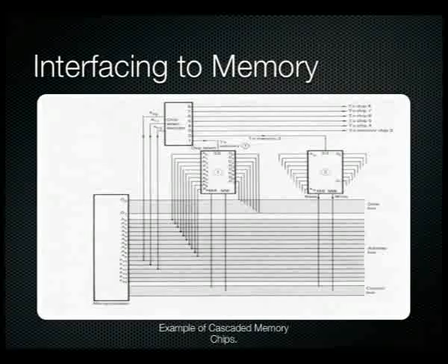In this example, we're only showing 2 in the picture, but effectively there are 8 different 1K chips. So we've got 8K of chips, 8 of them, and using those 3 address lines, A10, A11 and A12, we can pick which one of those 8 chips we want to turn on.